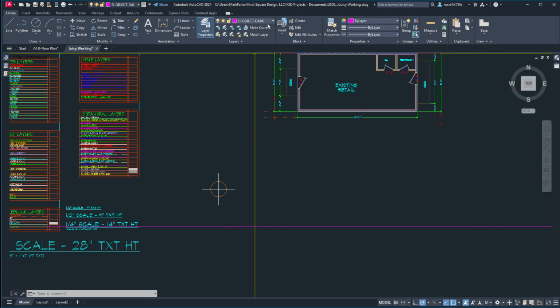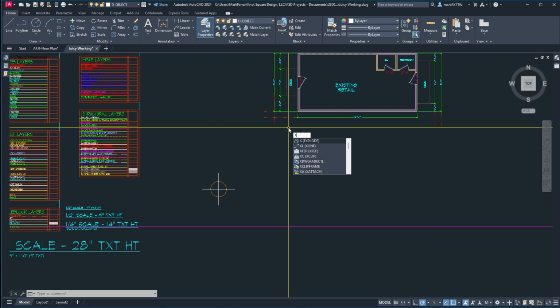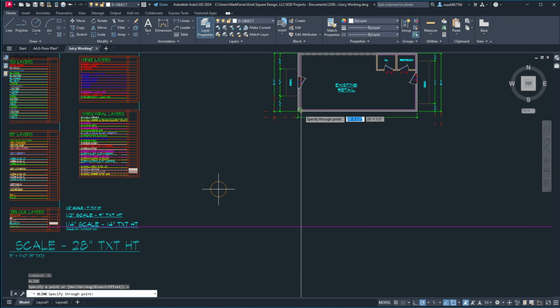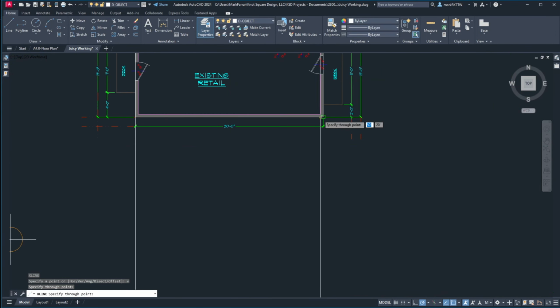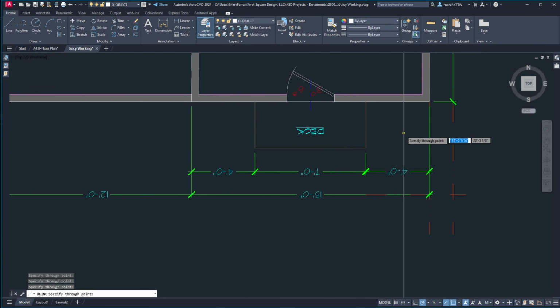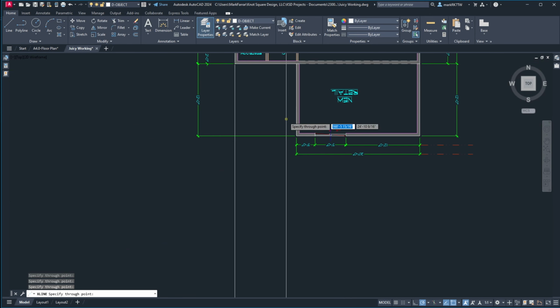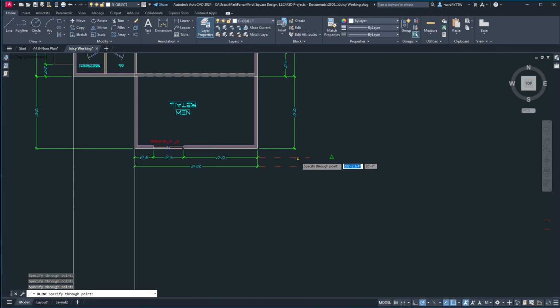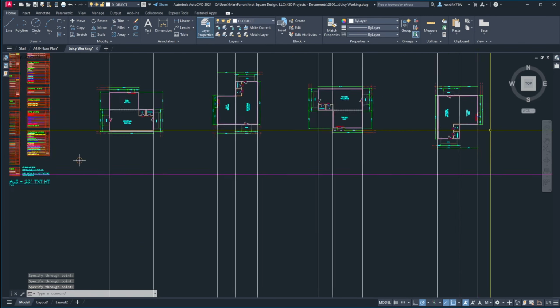So now that those are in place, I can switch over to just the object layer, do an XL, put it on vertically, drop one here, and I'm going to do the elevations first. I usually do the section first, but I don't have enough site information at this point in time to truly do that correctly. So I'm just going to drop in lines to start an elevation using the data that I was given from the project owner.